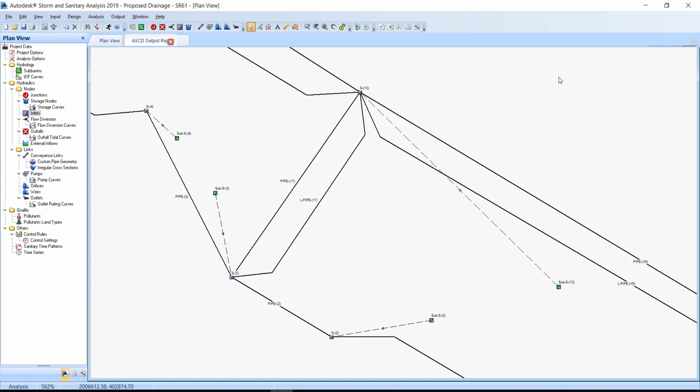Surcharged pipes and oscillations. If the upstream end of the pipe surcharges, then a head adjustment is performed by the routing engine at the upstream connecting node. Because this head adjustment is an approximation, the computed head at the upstream node can sometimes have a tendency to bounce up and down or oscillate when the pipe first surcharges. This bouncing can sometimes cause the analysis results to become unstable. Therefore, a transition function is automatically used to smooth the changeover of head computations.